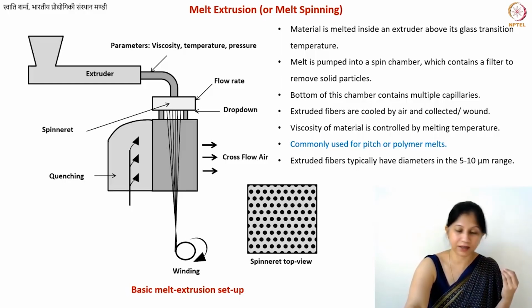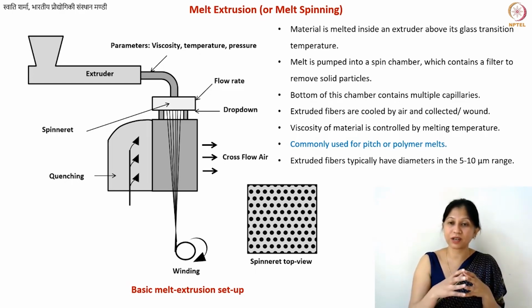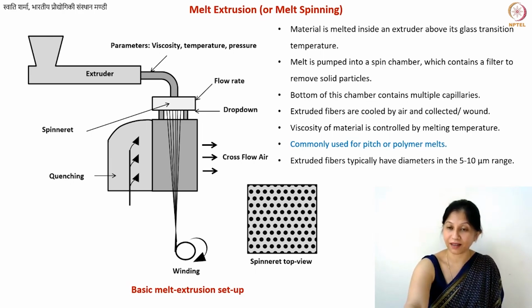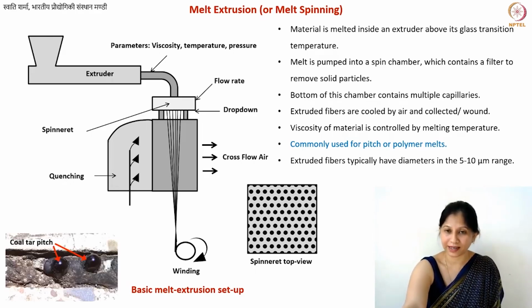The shrinkage patterns in the case of fibers are also different from what you have for bulk industrial carbons, because there you have much more shrinkage due to much more mass loss. Here you will have much more surface area, so your defects or byproducts can anneal out easily, and you don't get as much shrinkage as you would in the case of bulk materials. And we are going to discuss why that happens.